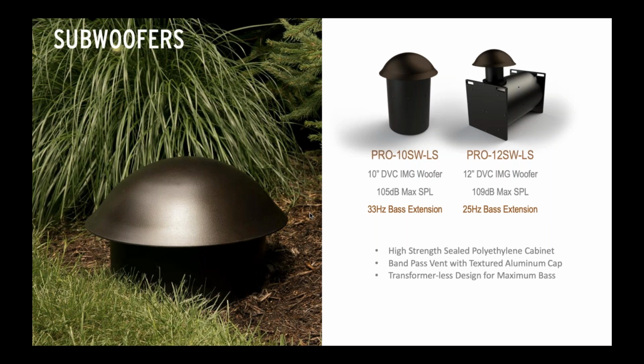So you are getting the convenience and the ease of a 70-volt install, but you're not missing out on all of that low frequency extension that you typically lose in a 70-volt situation because of transformer saturation.